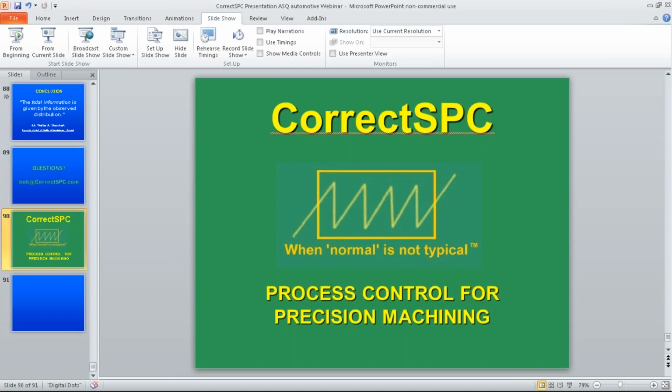And even when I'm calculating capability studies for a customer, that's what I'm going to do, is do a high and low. I'm going to say this is where we adjust it, and this is what the process looks like, because that is a true evaluation of what the process variation is, not some single calculated index, because that doesn't really tell you anything about what that process is going to do over time.